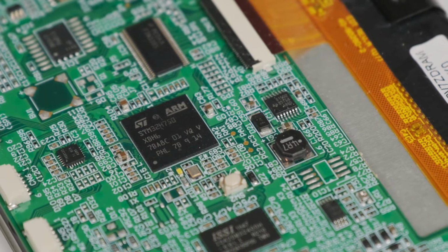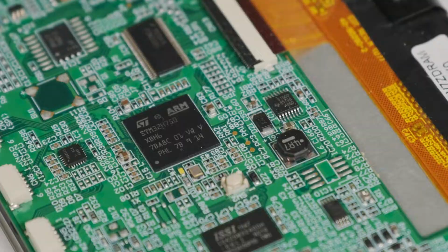Before we dive in, we are talking about industrial displays. Typical sizes would be 4.3 or 7-inch. Smart Embedded is a display with an integrated Cortex M7 controller with, for example, 480 MHz, plus a QSPI flash, 32 megabytes, 64, 128, whatever is needed for your application. And these displays are already equipped with a number of industrial interfaces. A necessary power supply ranges from 7 to 36 volt with several options, such as power over Ethernet.